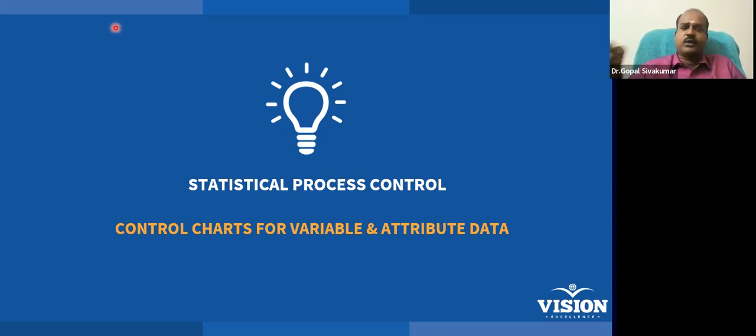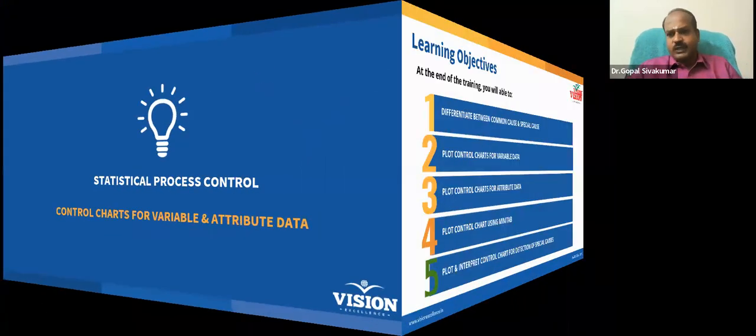If it is not under control, your primary job is to bring it under a state of control. We also call it statistical control. We also call it stability. So what is this statistical process control? How is the control chart helping us? The terminologies used in the field of statistical process control, that is going to be the first session. And then towards the end, I will tell you how to conduct the capability analysis. And then we will also measure the capability in terms of Cp, Cpk or Pp, Ppk, according to the requirement. So this is going to be my talk.